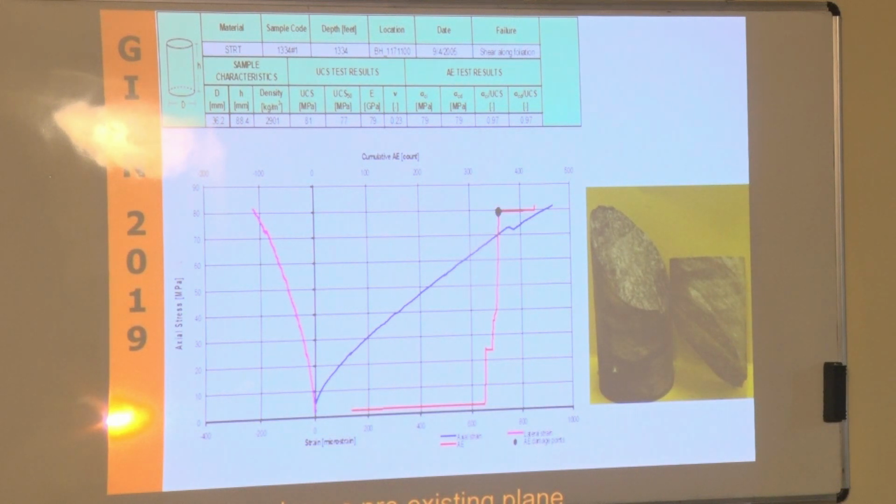Plus, and I just throw that in now, there is another way to calculate the elastic properties of a material. So one is testing, this type of testing. The other one is basically using ultrasonic P and S wave measurements. Do you know what P and S waves are? Basically you have a probe on one side and a receiver on the other side, and you are hitting the system with waves.